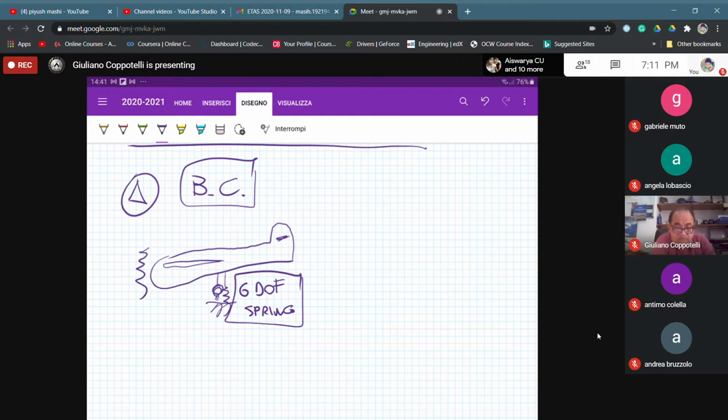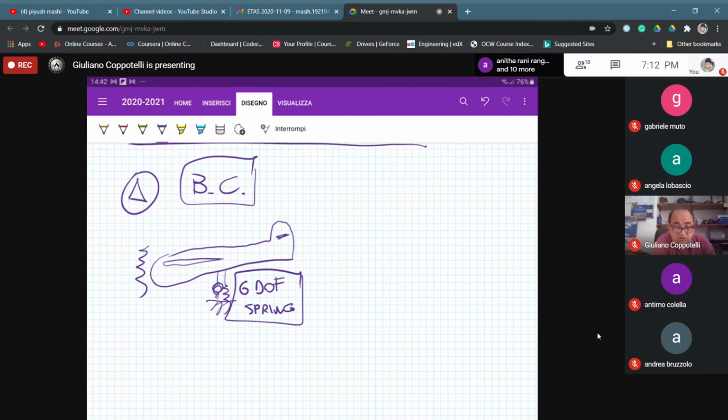Thus, when referring to an aircraft, we are referring to the flying condition because it's a self-sustaining structure. All the boundary conditions, the true boundary conditions, are there. Remember the connection between wings and fuselage. The effect of the supporting device is very local, so we try not to introduce that in your measuring chain, and therefore you are having a quite good representative measurement of the actual reality of the defined aircraft.